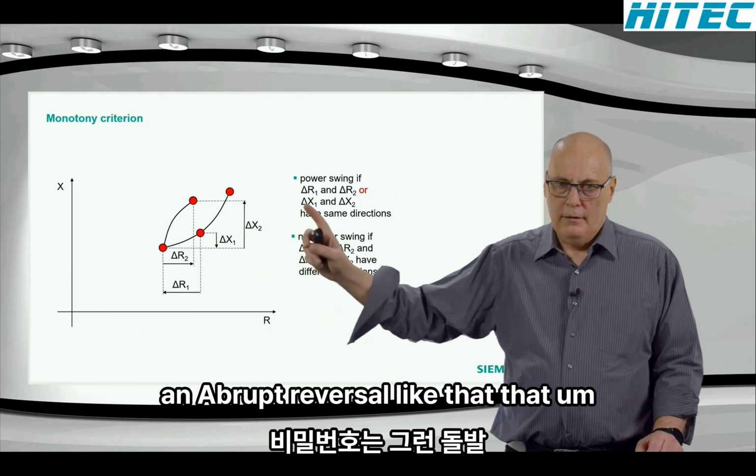That's from basically here, 0 degrees back to 0 degrees. That's one time around the circle. And you take the time difference there. I can't read that exactly now, but that would be related to the frequency. I think it's around from 2.5 seconds to just under 3 seconds, so it's just under half a second. So it's roughly a 2 to 3 Hertz swing. But you see, as we move on, the interval gets shorter and shorter. The swing frequency is increasing. So at that point, we have around a 2.5 Hertz swing, and then right at the back, we have an interval of only about 250 milliseconds, around 4 Hertz at the end. So the swing frequency changed there.